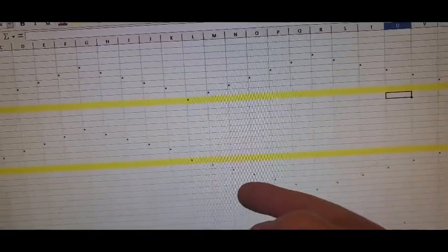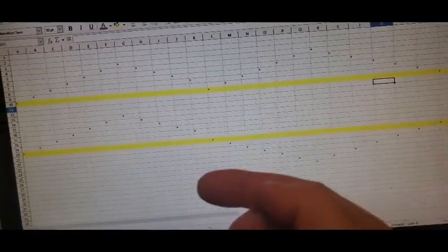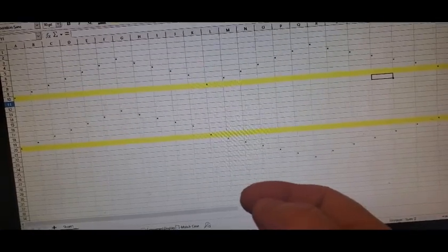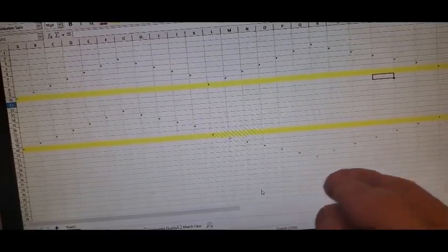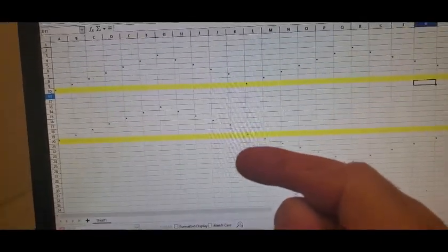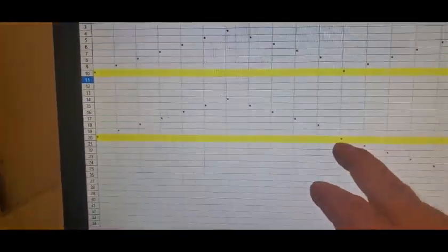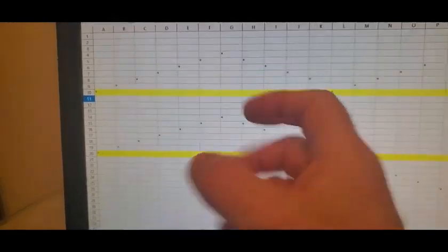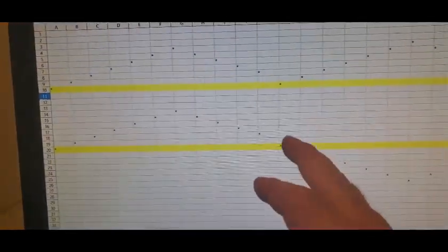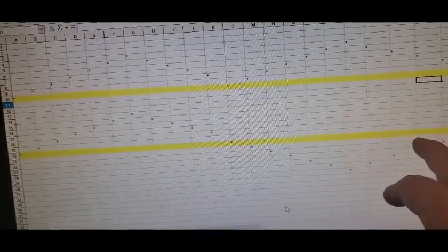It's not only not going to rectify, remember that it just needs 0.6 volts to start flowing with next to no resistance. And so here it's in a blocking configuration, capturing that backwards spike. Here the thing's already backwards, and it can flow right through the diode. So, oh no, what do you do now?